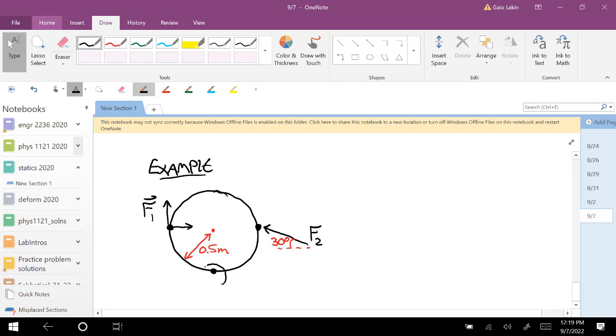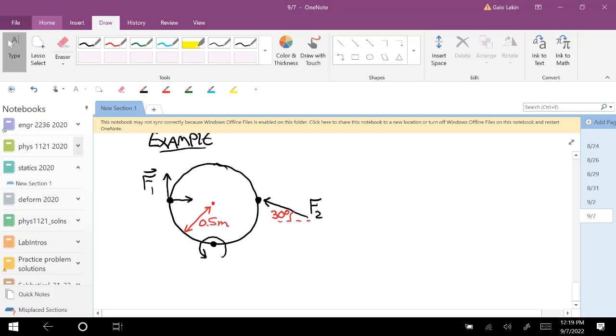And then down here, let's say that there's a couple applied. That's the default direction, and let's say that it's negative, which means really, and it has a value of 450 Newton meters. Okay, which we could write exactly equivalently with the arrow going clockwise, and that is a positive 450. Okay, that's what those negatives mean.